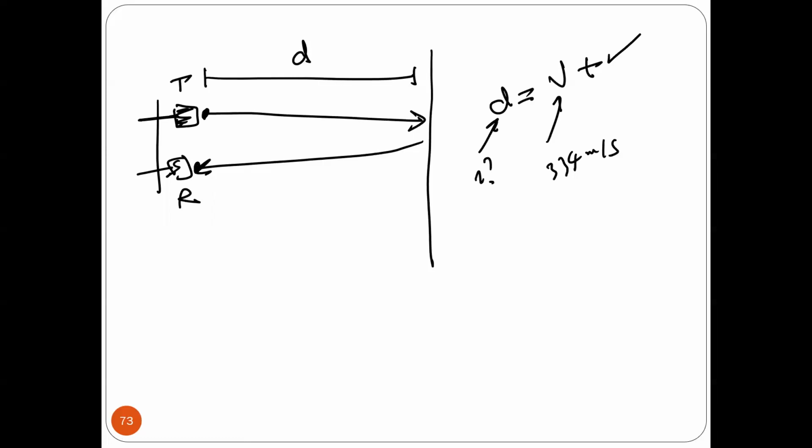So now the question is how I'm going to use it. Very simple. Number 1: the transmitter has a pin, connected to the microcontroller using one pin. The receiver also has a pin. Every time I want to do a measurement, I have to generate a pulse this way. That's easy to generate, right? It's just one pin: high for some time and then low. That's it.